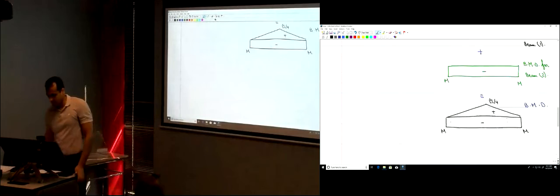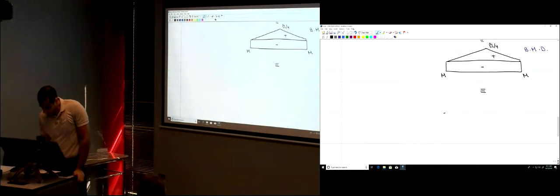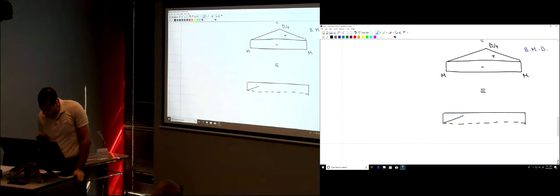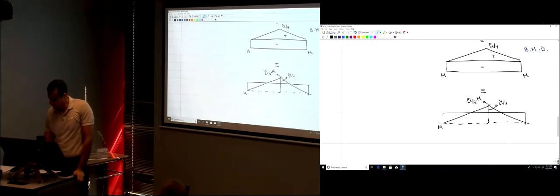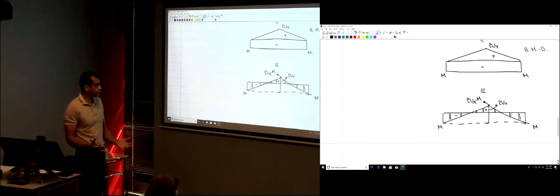So mainly this is the equivalent. It's negative M, this is a dotted line, and then I'm adding here, or subtracting from this M, PL over 4. That means that this point here is PL over 4 minus M. This is M. If you're going to do the hatching, this is how it should look. This is negative here and positive here. You understand what I'm doing?